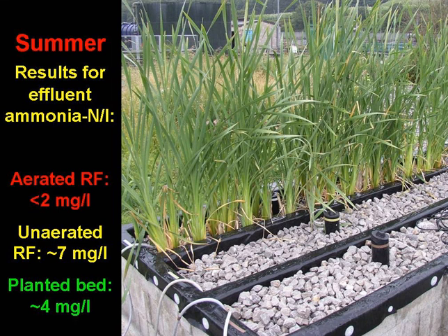The units were identical in size and they were fed facultative pond effluent rather than maturation pond effluent as in the USA. They were all subsurface horizontal flow reactors loaded at the same hydraulic loading rate with a wastewater depth of 50 centimetres. The aerated filter was supplied with air from a compressor at the rate of 20 litres per minute. The results in summer were excellent.